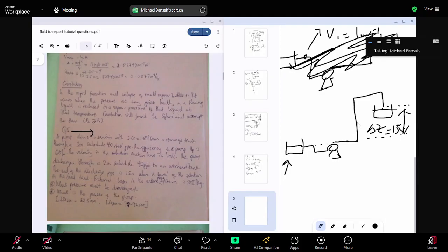Frictional losses in the entire piping system is 30 joules per kilogram. And note this, they said the entire piping system is 30 joules. So it includes the pump and everything, the pipe connected to the pump. That is the system. So it includes the friction in the pipeline and the friction in the pump, and it is giving us 30 joules per kilogram. So our work has been made easier.